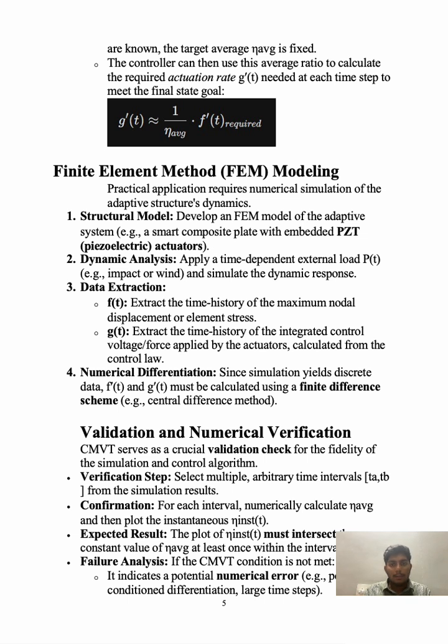Finite element method (FEM) modeling. Practical application requires numerical simulation of an adaptive structural dynamic. There are four steps: structural modeling, dynamic analysis, data extraction, and numerical differentiation. Let us discuss structural modeling. Develop an FEM model, meaning a finite element model, of an adaptive system. Example: a small composite plate with embedded PZT actuators.